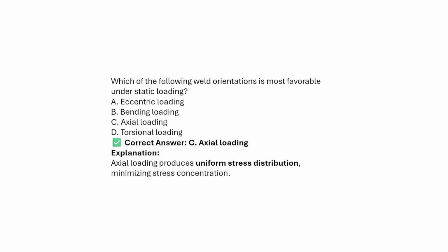Which of the following weld orientation is most favorable under the static loading? Eccentric loading, bending loading, axial loading, torsional loading. Answer will be axial loading. Axial loading produces the uniform stress distribution and minimizes the stress concentration.